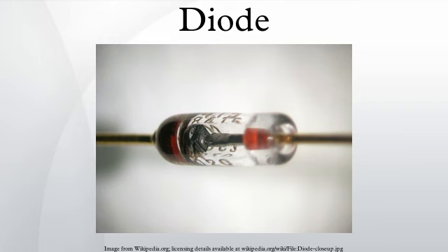Thermal diodes. This term is used both for conventional PN diodes used to monitor temperature due to their varying forward voltage with temperature, and for Peltier heat pumps for thermoelectric heating and cooling. Peltier heat pumps may be made from semiconductor, though they do not have any rectifying junctions. They use the differing behavior of charge carriers in N and P-type semiconductor to move heat.